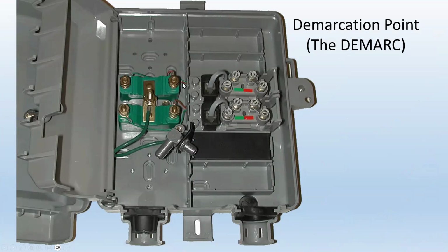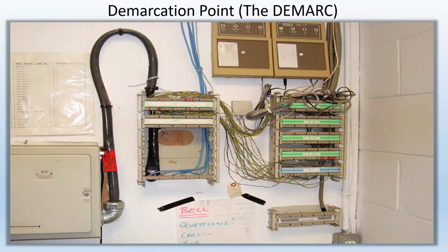And you can see here there's a pair of wires, and here there's a pair of wires connecting things to this jack. This one connects things to this jack. You can plug that in to activate these two tip and ring here, or this tip and ring, and from here the wire goes to the inside of the house. That's how this one works. All right, here we have a typical demarcation point.